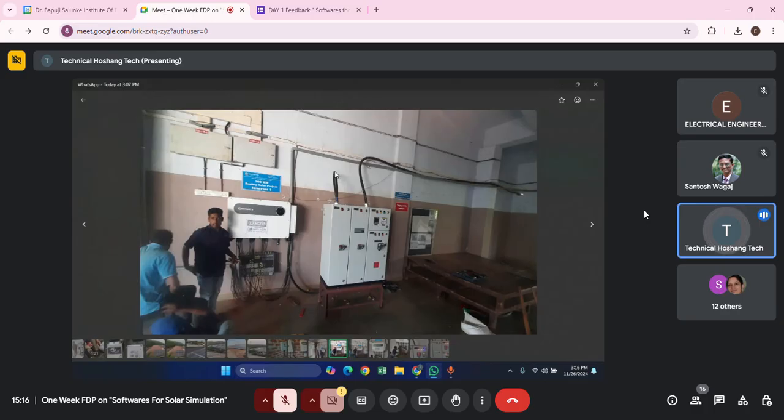So this is the input terminal for inverter 1. This will be the outgoing terminal, and another cable which we entered later. This is the chamber for one inverter and for another inverter, and this is the main safety feature device. So we have a simple connection made here with this 185 square mm wire, and on a temporary basis it was directly laid. Later on we have a proper tray for it, and then we have taken it directly to the generation meter room, or let's say the LT panel room.